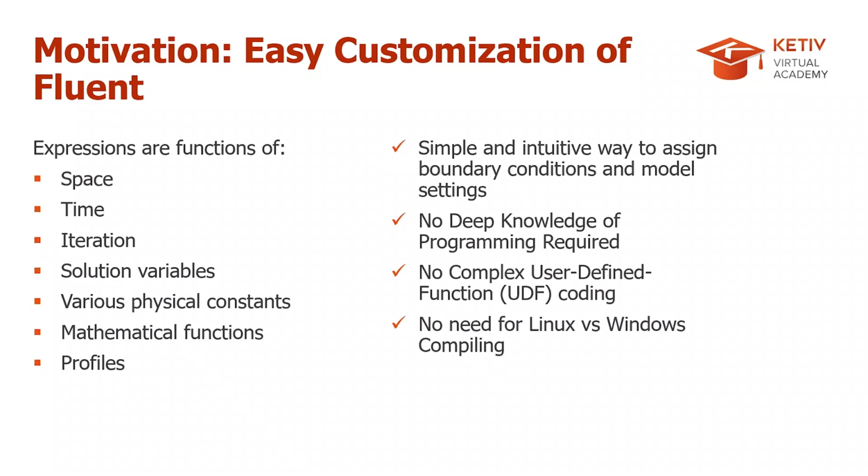Those are written in the C programming language. And if you're not very familiar with the C programming language, then it becomes a whole lot of effort to understand how to write UDFs, how to interpret the different macros or different variables that go into writing simple functions for assigning complex boundary conditions and settings. So instead of doing all that, we can use expressions. It becomes much simpler to customize settings for your problem.